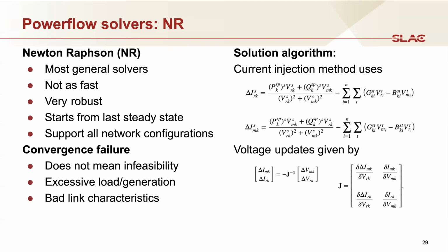So generally, the longest solution is the very first solution, when it has to start from a cold start and it doesn't know the initial conditions. If you give it pretty good initial conditions, you can even make that one go fairly quickly. So this Newton-Raphson solver is quite flexible, and really good for all the various configurations we might find in networks.